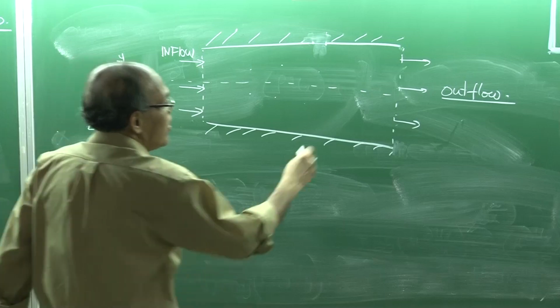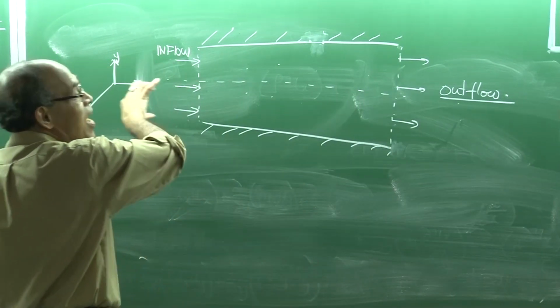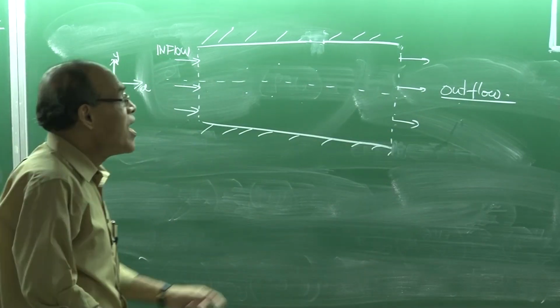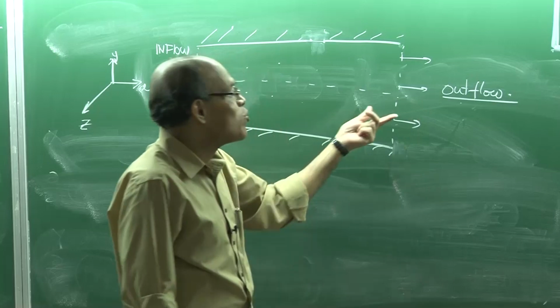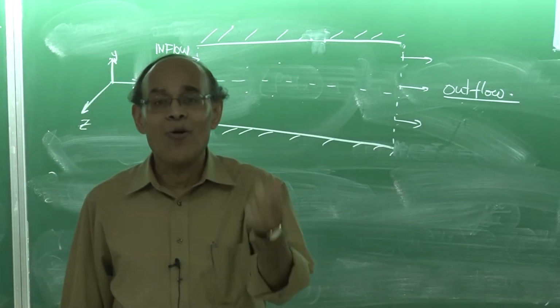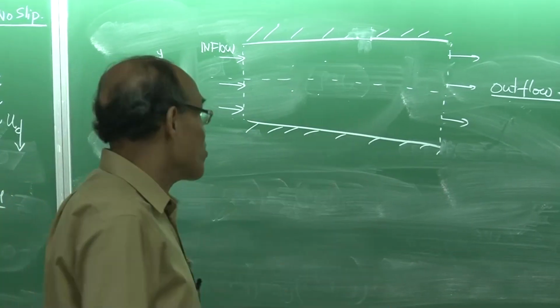So, basically, outflow must satisfy the mass continuity, that whatever mass is coming in at steady state, the mass will be going out from the system. That constraint it has to fulfill, and then by assuming that the flow is one-dimensional, which we call the standard outflow boundary condition, at the outflow, diffusion will be set equal to 0.